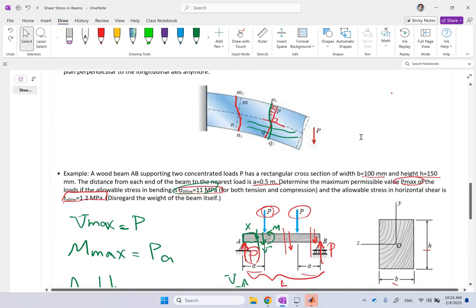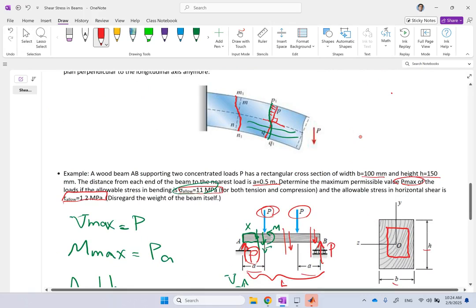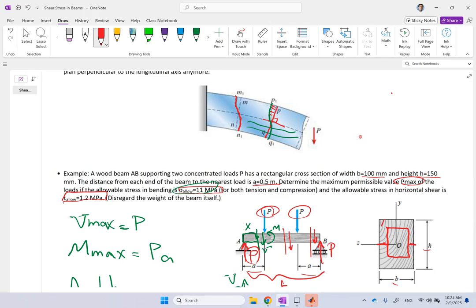And if the rectangular cross section is hollow, still you can do that, okay? Still the max happens here, with the difference that now your Q is going to be for this part here, which you have to find the centroid of and multiply by the area to get the Q. I is still the same I, except this hollow part should be subtracted.